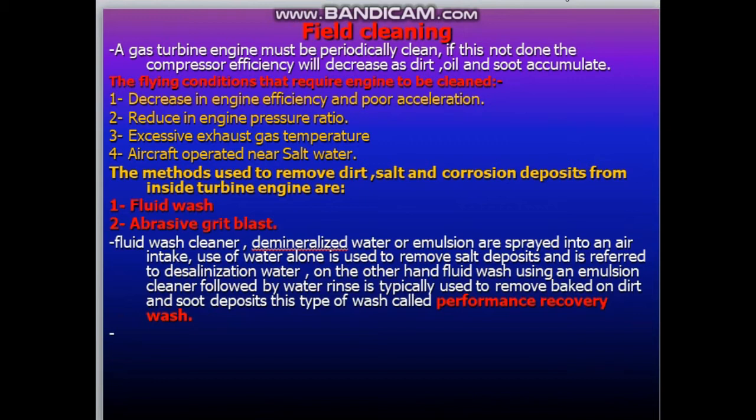The second one, reduction in engine pressure ratio. The third one, excessive exhaust gas temperature. The fourth one, aircraft operated near salt water. So if one of these happens to our aircraft, you have to make cleaning for the aircraft.